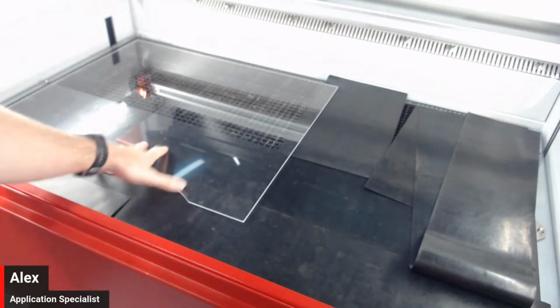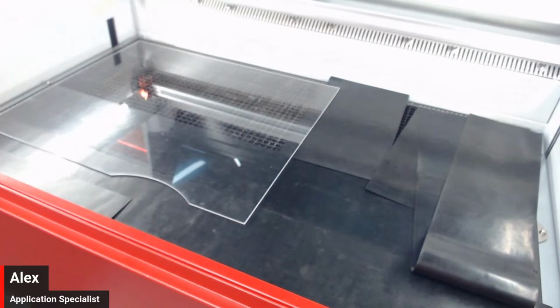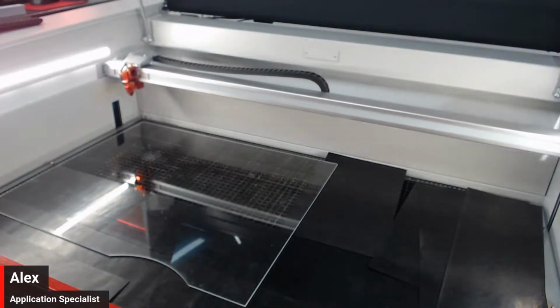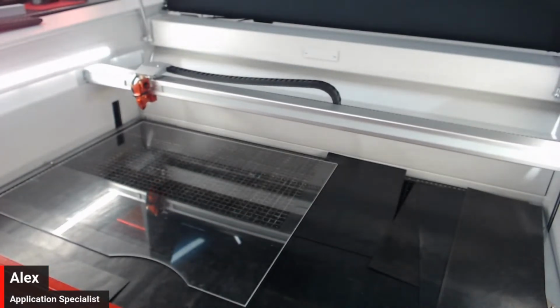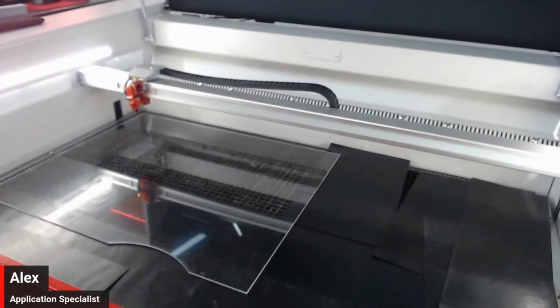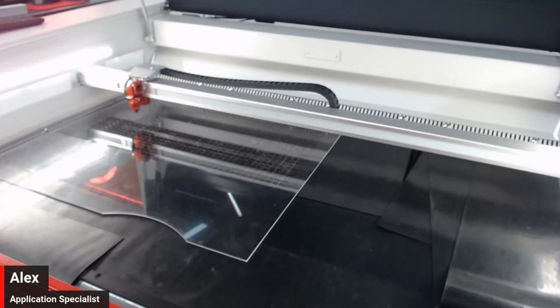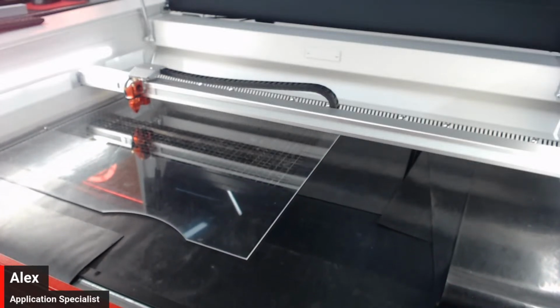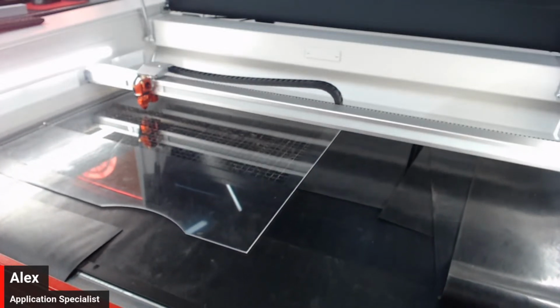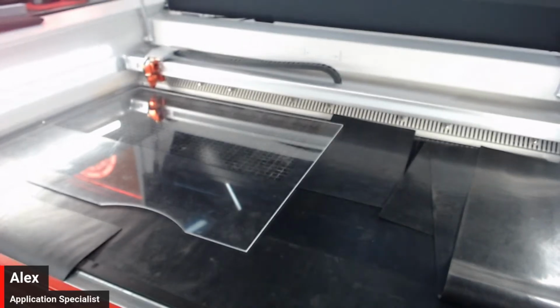Most people tend to push the material to the top corner of the bed, and then we move our laser head above the material, and then you obviously set your focus. For a lot of machines that may be with a manual tool, but this machine has the sonar sensor built in, so it's just going to take the measurement of the height. And now the machine is ready to operate.